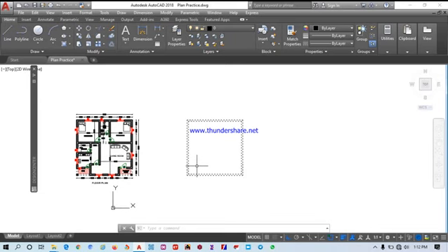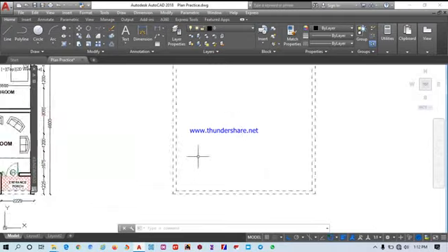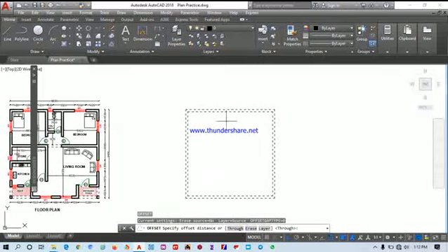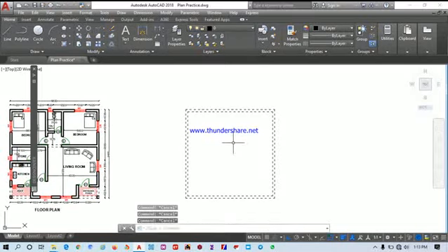But in some recent buildings that we have these days, you see what we call concrete fascia. So that's the order of the day right now. But let's make use of this old design. So we'll go to offset. This is offset on modify. Then you type 600 on your status command bar. Sorry, you have to offset 600, not 6,000, 600 on all the 4 edges.